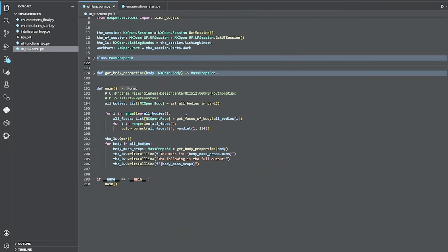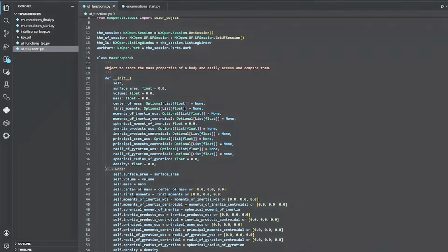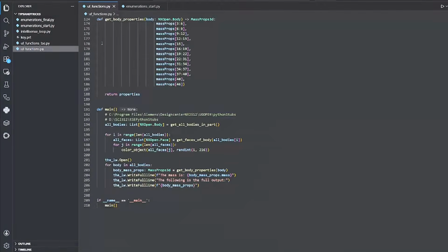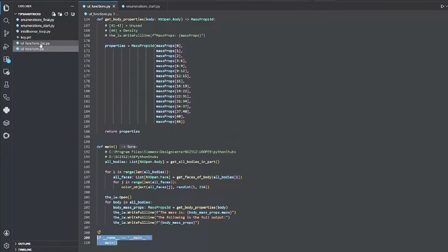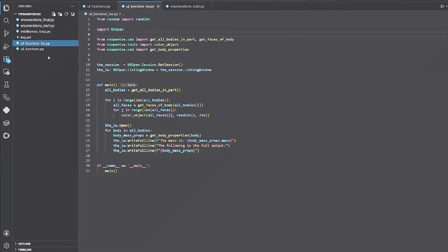One thing I wanted to show you here is also the benefit of this. Because I copied these functions in, the total length of our, let's say, very simple journal is about 200 lines. If we simply import all that functionality from our nxopentse package, with shared code in there and wrappers for all sorts of functionality, we can have that same code in 30 lines.